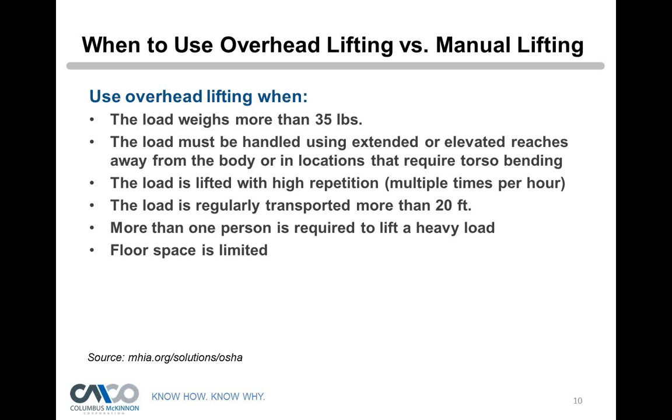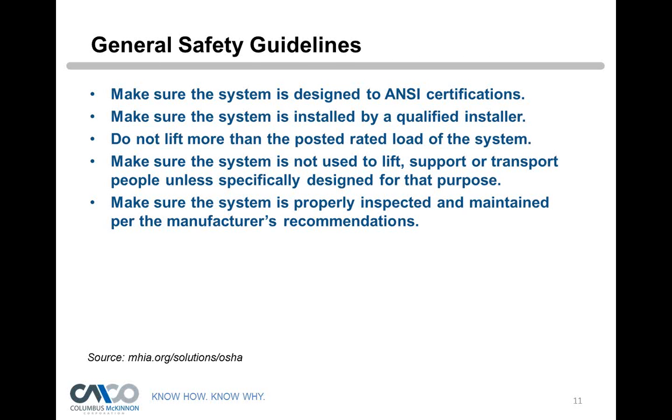When more than one person is moving it, and also when the floor space is limited, so you may have conveyors, you may have high-lows coming in and out of the area, something to take away from that potential hazard of a person moving the load. Some general safety guidelines I'd like to just go over real quick.